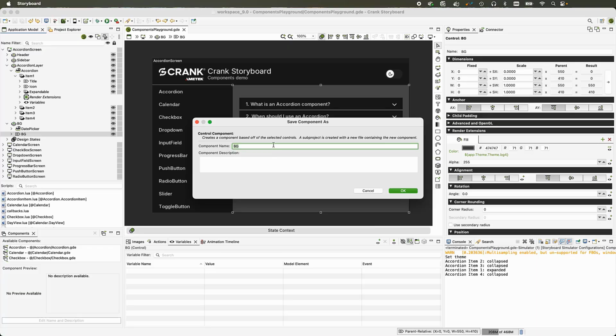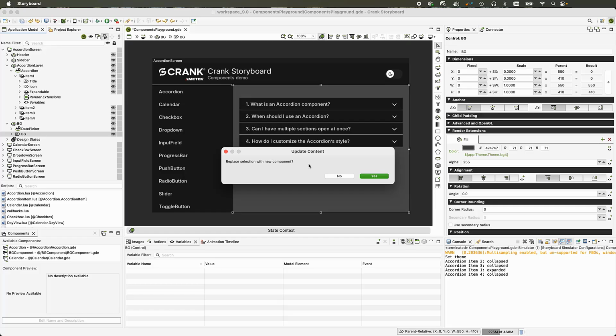And when you create your component, you're going to need to specify its name, and then you can just give it any description that you'd like. The name is important, though. Once you create a component, its name is going to become a keyword that is going to enable some of the functionality I'm about to talk about. So be careful to name your component properly, because you're not going to be able to change it after, or risk breaking some of the functionality.